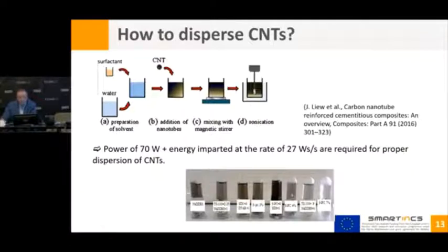And of course, the fact that the solution is darker respect to the previous one, considering the same concentration of nanotubes that were dispersed in all the tubes, means that if the solution is darker, the dispersion was better, because we were able to separate in an efficient way the carbon nanotubes. But we will talk later about the tests we can do to evaluate the dispersion.